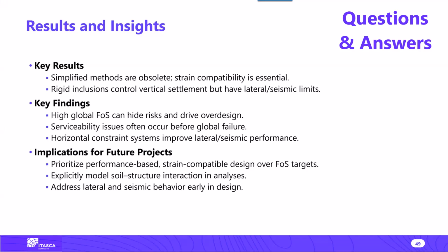Great. Were you able to capture stress rotations and arching at the top of the rigid inclusions, or did the behavior resemble more a pyramid between the inclusions? That's a very good observation. I would say it depends on the relative stiffness of the embankment, and it depends on the height of the embankment. But typically, yes. It also depends on the spacing, right? So you have to have a certain ratio so that you would be able to form that dome effect between them.